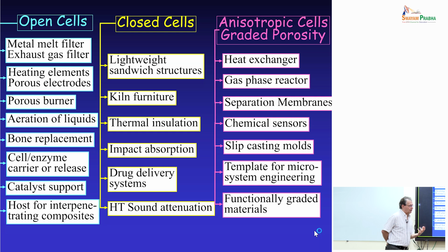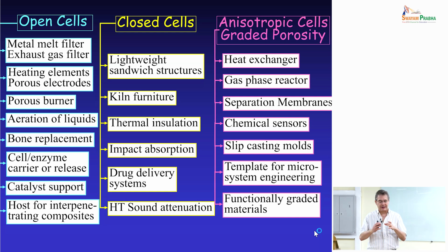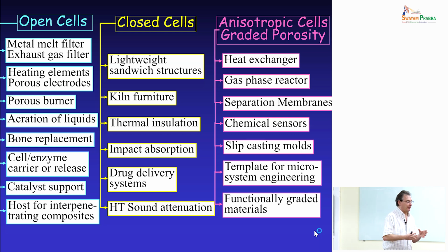And one interesting possibility that I didn't mention is that if you have a cellular ceramic, you can infiltrate it with metals, or you can infiltrate it with polymers. And what the ceramic does is that, of course, it provides characteristics to the bulk material that the material itself wouldn't have. So, for instance, we infiltrated ceramic foams with polymer, and then we created some components for bullet-proof applications. If you infiltrate with a metal, you can generate a very strong interface between the metal and the ceramic, which is positive.